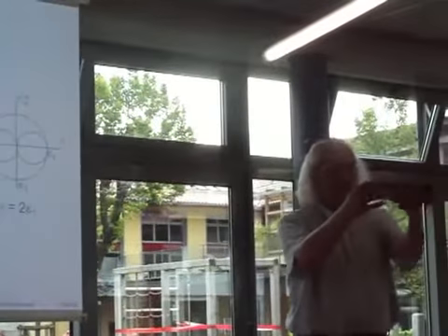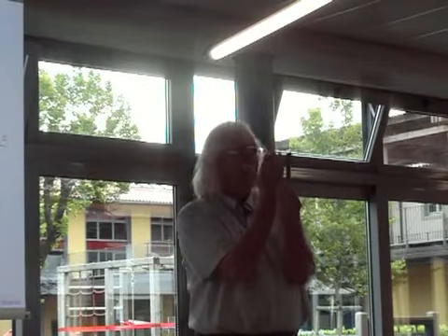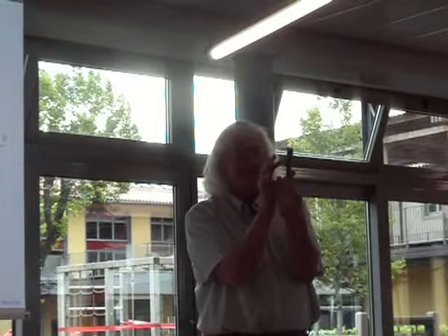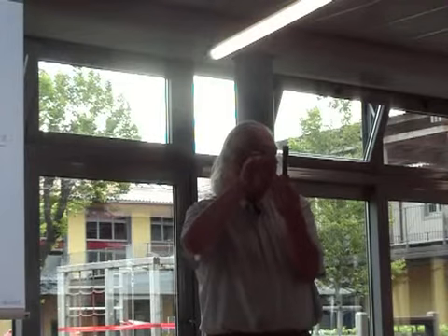So let's just think about what this tells us a little bit. When I load this in tension, and I nucleate a crack in shear with some stress level, whatever it is, the shear stress that acts on this plane is only half as much. So once a crack starts to form, there's a big tendency to try to turn and grow into tension, because the tension stresses are twice as high as what the shear stresses were. And if you look at something in tension, you find that cracks nucleate and very quickly turn to try to grow in mode 1 in tension.